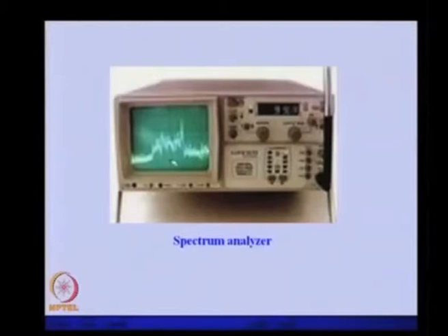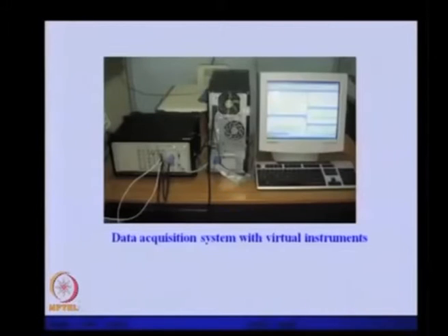signal in the frequency domain can be plotted apart from the simple FFT. Or if required, we can transfer the data into the computer through a data acquisition system, and here we can have some kind of virtual instrument. So, depending upon the need, what kind of processing we want to do, we can make our own instrument virtually, and this will display various forms of the signal which we want to monitor. This is very handy, that whatever signals we are capturing, we can directly process it and display it on the screen directly online.